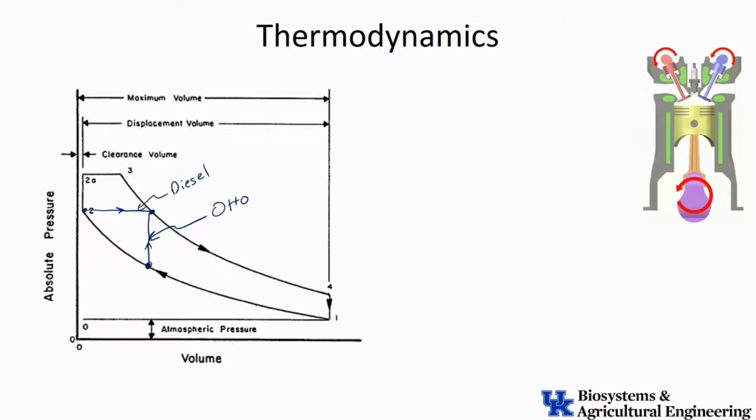If we get much lower than that, this curve, of course, is turning asymptotic, and so our pressures would go really, really high, and we would start to reach physical limits of the engine. When we start to break stuff, it's going to start to explode. So that's kind of the pressure where we get to. We ignite the fuel, and we get an immediate pressure increase. When that fuel ignites, as the piston starts moving down, we're going to get some expansion at a more constant pressure. And then the power stroke after the burning is done, and that pressure is just pushing the stroke back down.